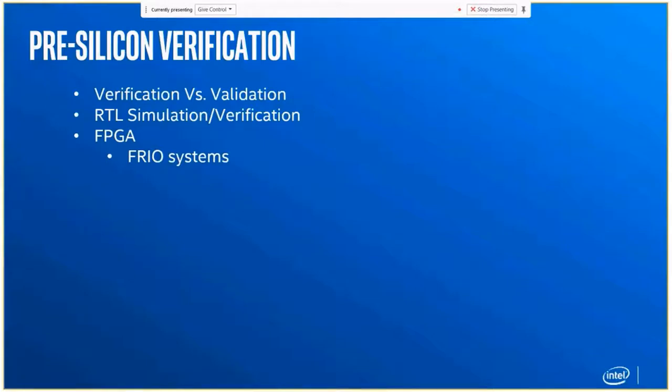FPGA, of course, is general purpose, so you can design whatever you want, and because of that flexibility, it will also be inefficient, so it can't be as dense as a real ASIC solution or an SoC is, right? So in the real SoC, take any block, MAC or something, you can do the whole block in so many square millimeters of area.